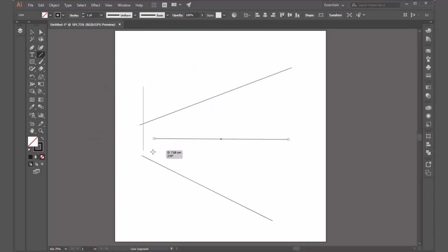So, for example, as you can see, again, 90. These are the famous angles. If you hold Alt at the same time, you can see drawing would be from the middle of the line. If you don't hold it, you start from the beginning of the line.